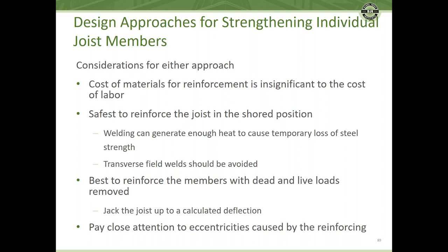Obviously, we're going to be perhaps cutting and welding on joists if it's up in place, and we need to make sure everybody's safe. Welding can generate enough heat to cause temporary loss of steel strength, and transverse field welds should be avoided because of undercut and those types of things that may damage the existing member.